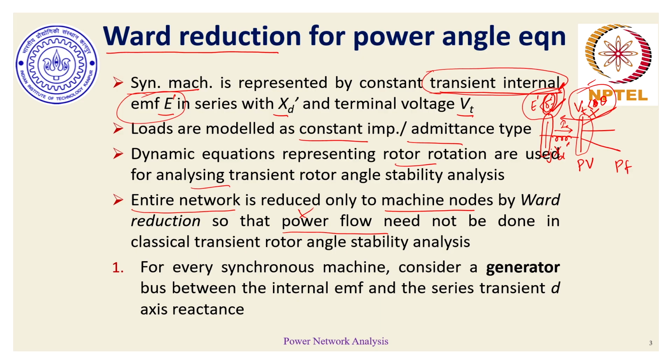It is not a steady state period. So while doing our calculations, if the number of equations involved are so large that the time taken to solve them is so large, the event might come and go by and our analysis might still not give us any relevant solution, because of which the corresponding corrective actions to maintain stability or avert instability might be lost. So that is the overall trade-off as power engineers, to maintain corrective decisions on corrective time with limited amount of computational effort involved.